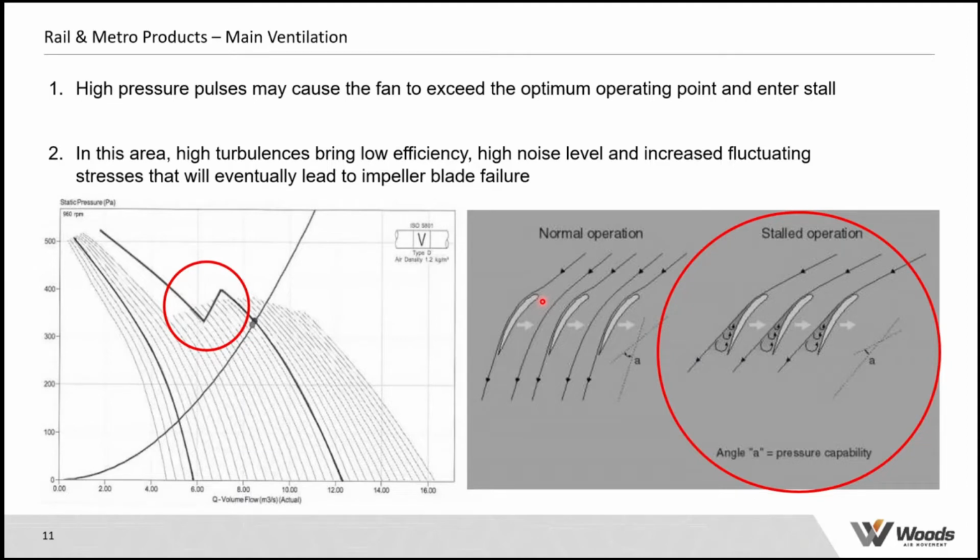That's aerodynamic performance. What you want is for the air, as it goes over the top of the aerofoil, to stick. And in this example, it does. But if that angle becomes excessive, the air can start to separate. So the air here is no longer sticking to this aerofoil section, it's carrying straight on, and then it creates this area of turbulence or vortices as the air effectively doesn't stick to the aerofoil shape anymore, and that can cause very high stresses on the blade.